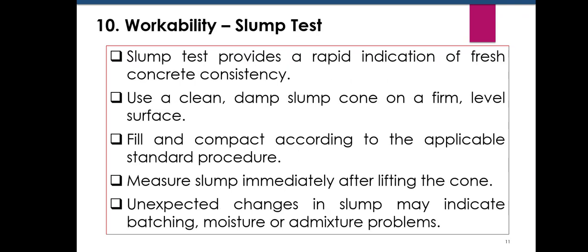So, next is the most familiar fresh concrete test, the slump test, to be followed at the site. The slump test gives a rapid indication of the consistency or workability of the fresh concrete. For a proper test, a clean and damp slump cone is placed on a firm and level surface. The cone is filled and compacted according to the applicable standard procedure. After the cone is lifted, slump is measured immediately.